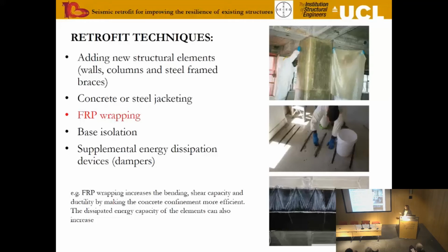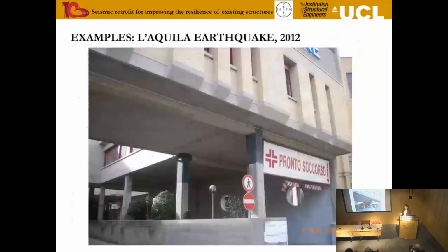Note here, the particular thing I want to show is this is not actually from a practical application that I've seen. It's from a guidance of good practice picture, and shows essentially that the wrapping for the beams is passed through the slab and anchored across the top. So it wraps the entire beam. In practice, that commonly isn't done.